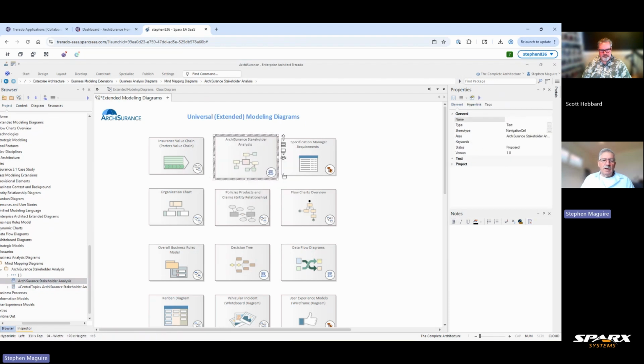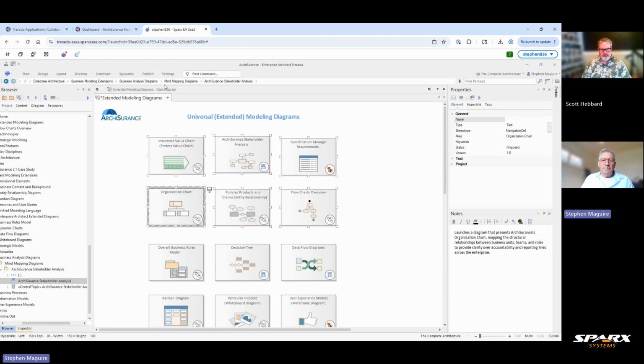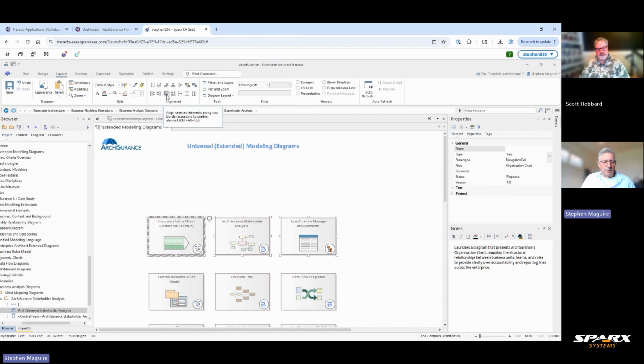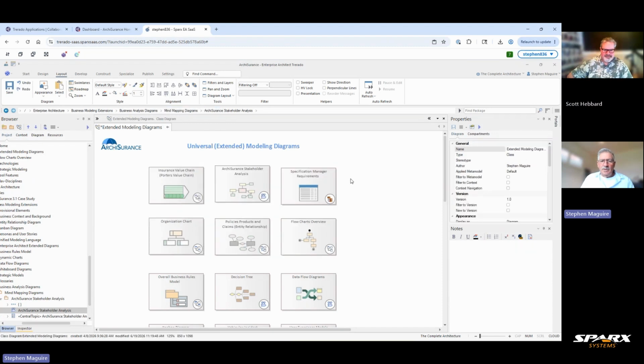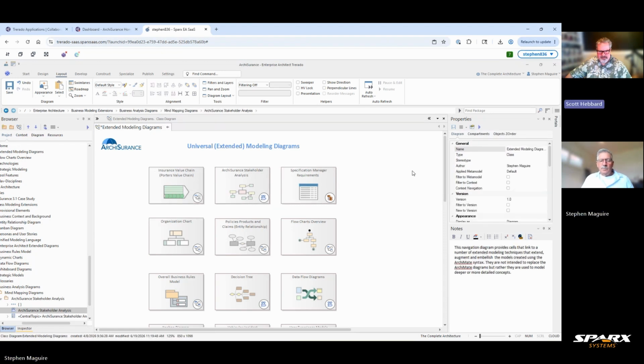Now we want to get these to the same size, so let's just select all of these and make sure that they're all the same size as that one. I go to my layout ribbon and I go to my alignment panel and simply select same height and width there. And then I can say, look, I want them to be lined up. So again, in my layout ribbon, I'm going to say, align their tops. Whoops, not all of them. A bit too keen there. I'll just align these ones here. So it's very easy to undo a mistake like that.